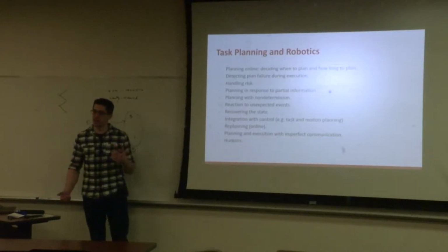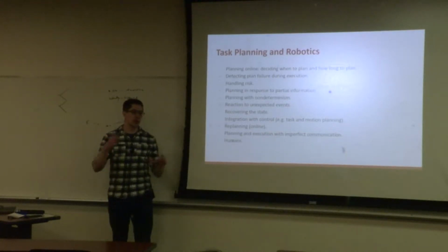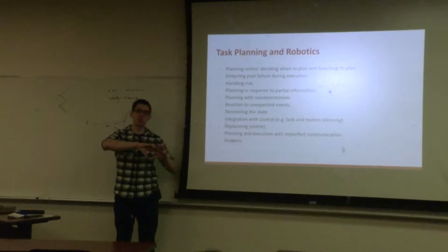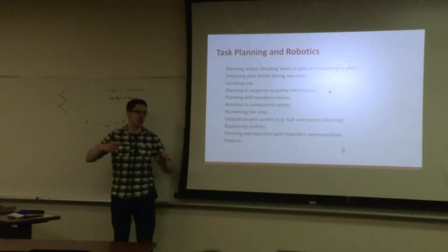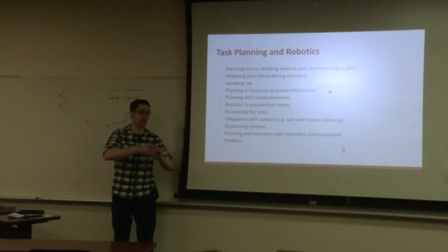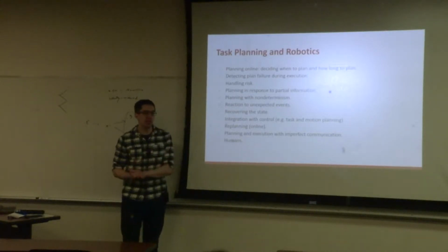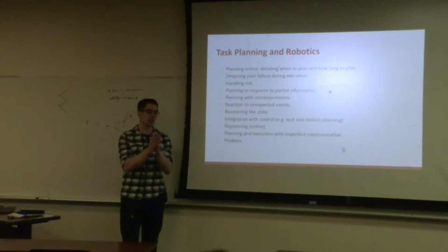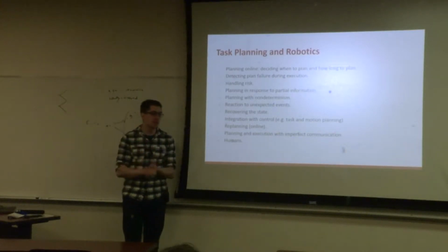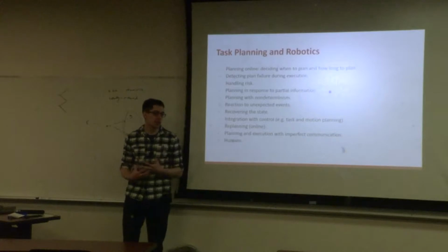So when something does fail and it needs to replan, the state that it's in could be somewhere between: the drill is gripping and it's digging correctly, but something else has gone wrong. It's come off the bottom and it's spinning wildly, or it's somewhere in between where it's sticking and spinning. What you really need is some sort of conformant operation where you can say, all right, I'm going to send some signals to the robot that will move it from whatever strange state it's in to exactly one of my modeled PDDL planning states. But whether that kind of command is possible depends again on the state space you're looking at.